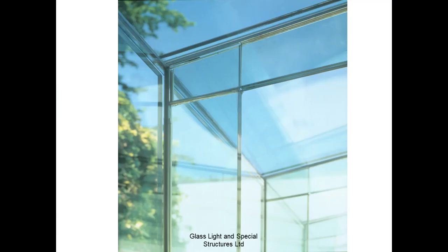Here's another building by Tim McFarlane, and this has beams and columns, of course, or ribs. I suppose we should say ribs, but this is a pure glass structure. The only other material that keeps this building together is silicone mastic, which glues the glass together. The joint you're looking at is known as a fritted joint.